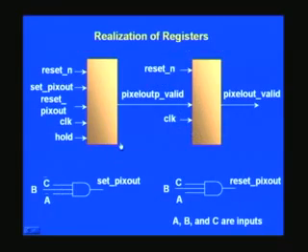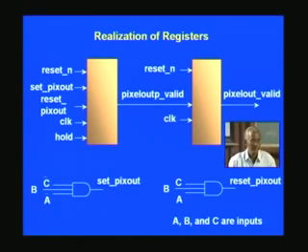Whenever you have a system, you may be processing at a very rapid pace, and there may be other systems, a host system, receiving this data. If this host is not as fast as your system, naturally the host will have to hold you for the time being. Unless you have a hold pin, it can't hold, and that is the provision made for that.